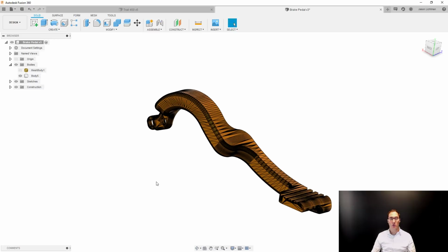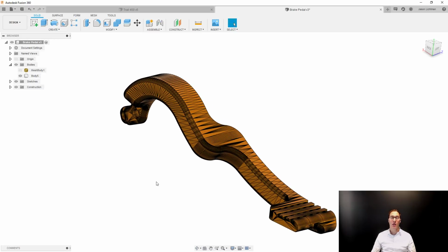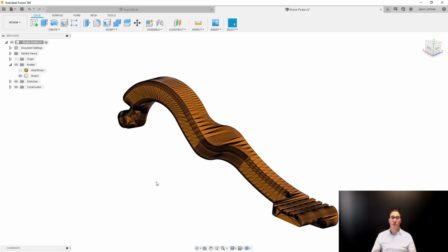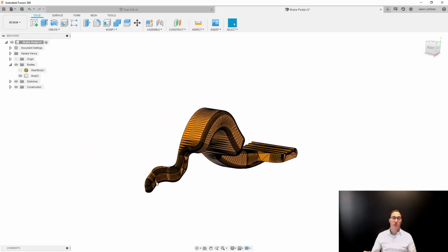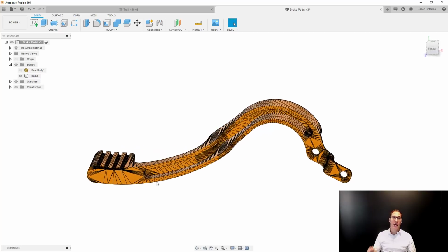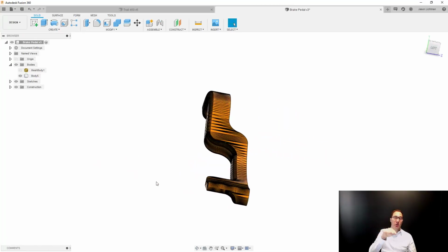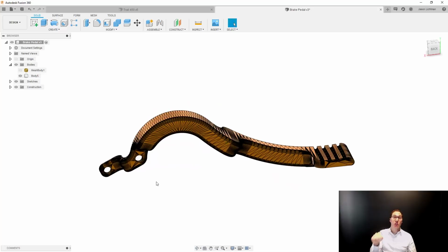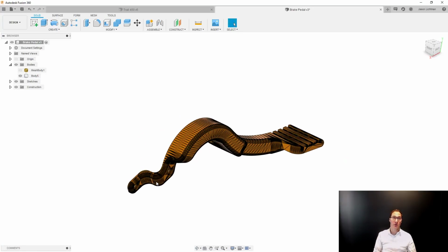So this also looks mostly the same as before. What it did was it converted each triangle that I had in the mesh to a triangle that's a BREP. And the reason that we said earlier that more than 10,000 is a lot is because every time you go to rotate this model, the software is actually calculating how each face is going to look. And right now I have just as many faces as I had triangles in my mesh.